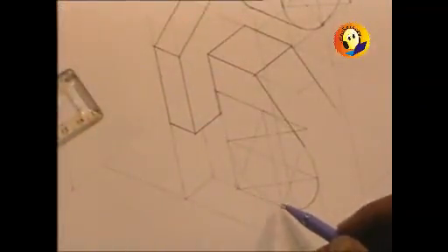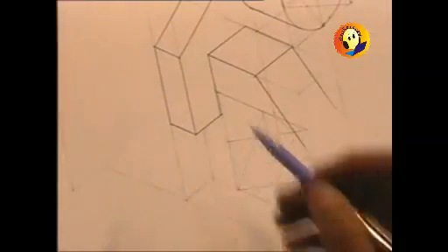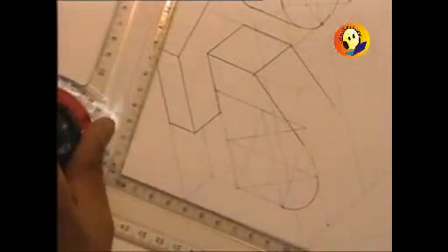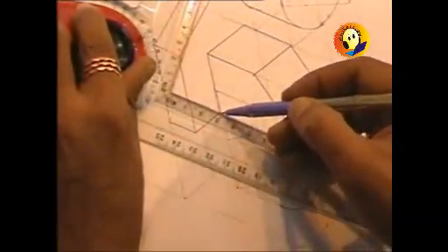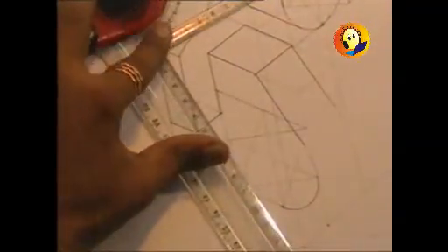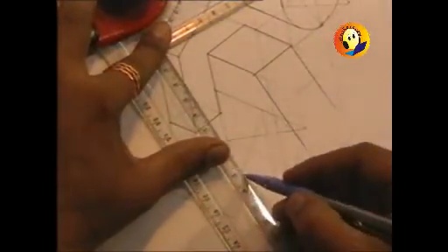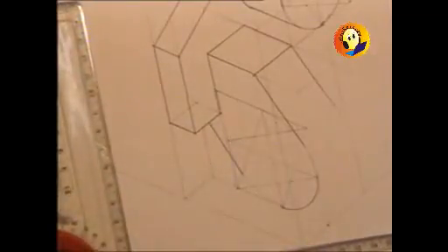And then if we go for the other tangent, then we know that that point is going to be behind, and I am required to locate that point from where the tangent should be drawn. That point is exactly behind this at a distance equal to 15 millimeters. So through construction you will have to actually show that point. And then the tangent should be drawn from that point to the ellipse. And of course only this much portion of that tangent will be seen, the rest is going beyond that 15 mm plate.